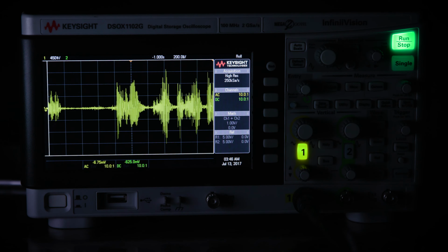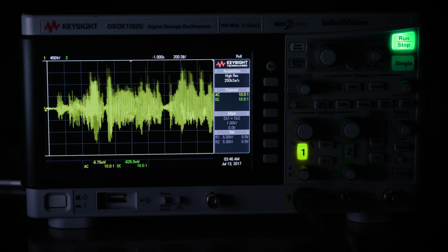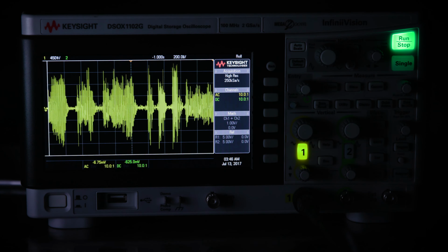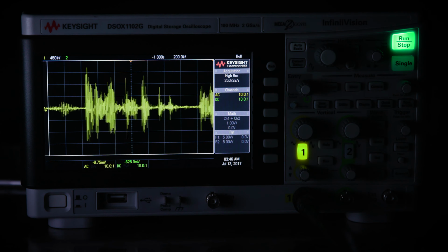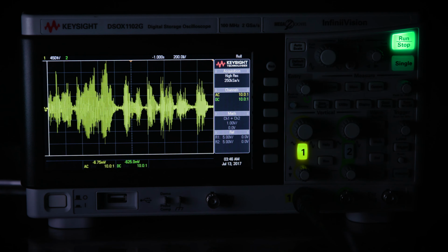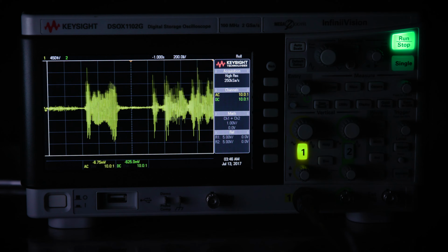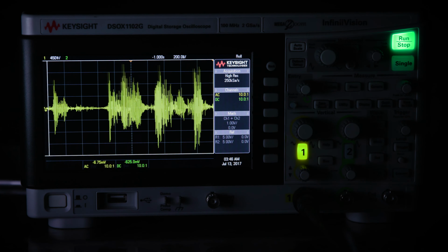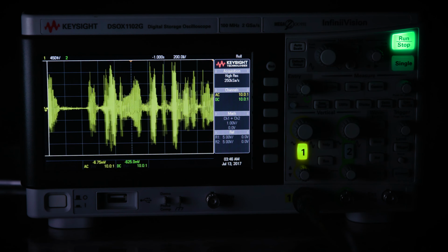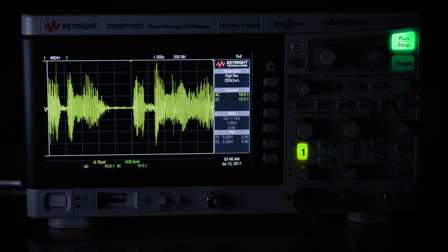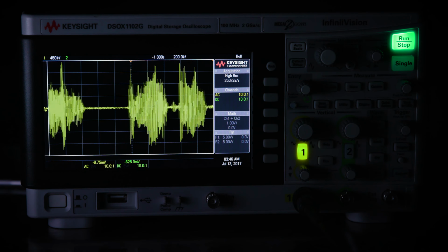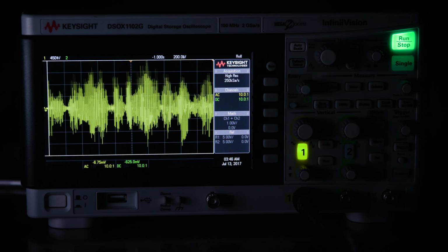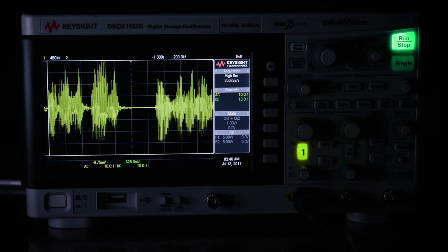So if your goal was not only to go from 80 gigasamples to 160 gigasamples, but also to go from 33 gigahertz to 63 gigahertz, you haven't accomplished your goal, right? You've only gone from 80 gigasamples to 100 gigasamples. So then again, you need a sampler out front that will take samples at the very high sample rate and feed them at a lower bandwidth to the even and the odd, or in many cases even like a switch, basically, like a high speed train conductor switch.